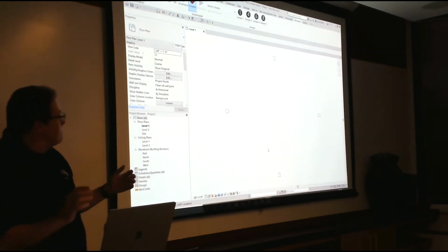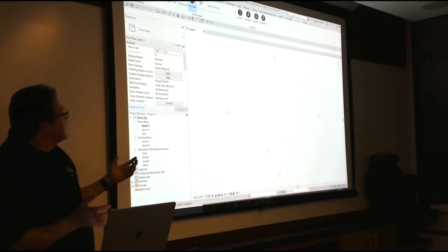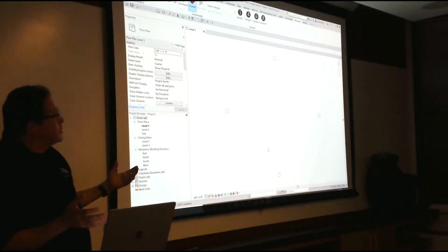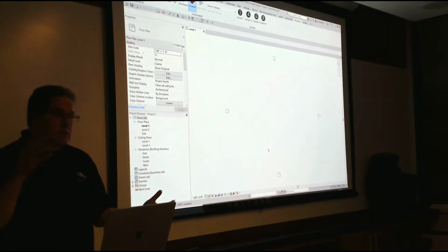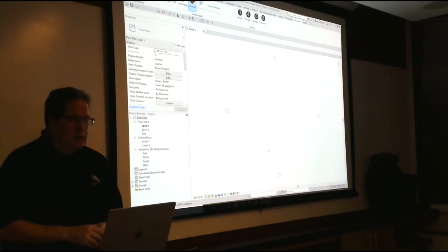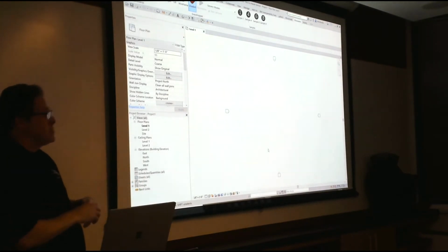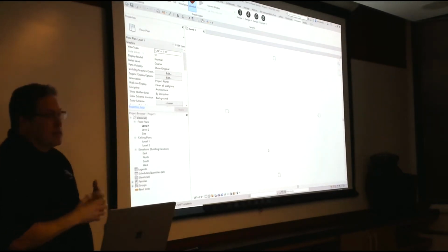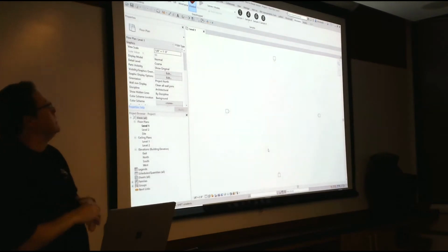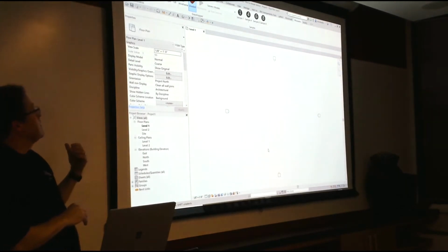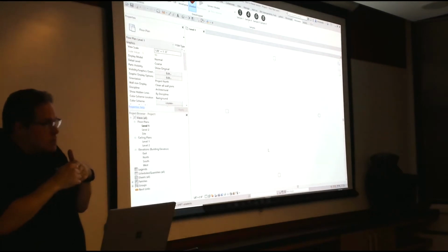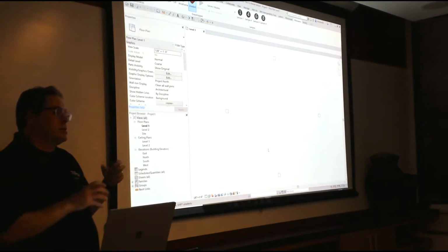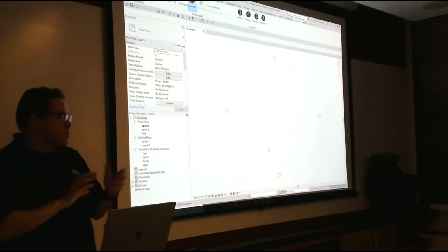Now, the reason we did this initially was that classic problem we talked about a little earlier: how do I get my Rhino information into Revit? It's always been a big divide. I always had to go through a file format. The file format stripped off a ton of information, and I didn't get to choose what that information was. Now you're going to see we can go data structure to data structure, and you can rewire how Grasshopper works to wire the correct information back and forth between the 2 products.